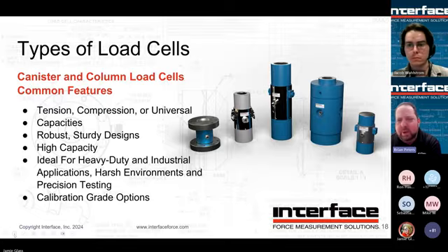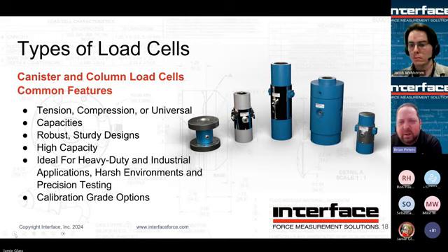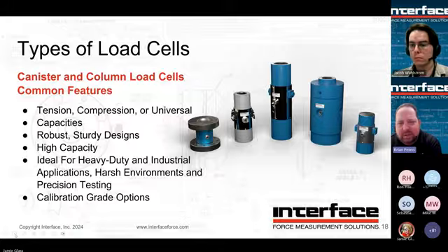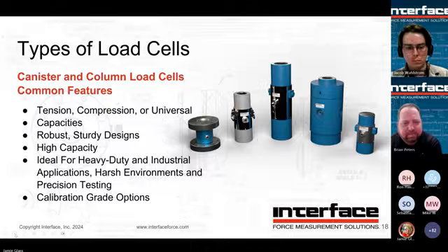Linearity and such may not be quite as good as some other models, but if you can scale that in your instrumentation, it's a non-issue. But again, we can seal them pretty well. That second unit in from the right, the all blue one that has very high hermetic properties, fully welded construction, Class B connectors, for example. So we can develop these into different ultimate form factors depending on what's required for the application.